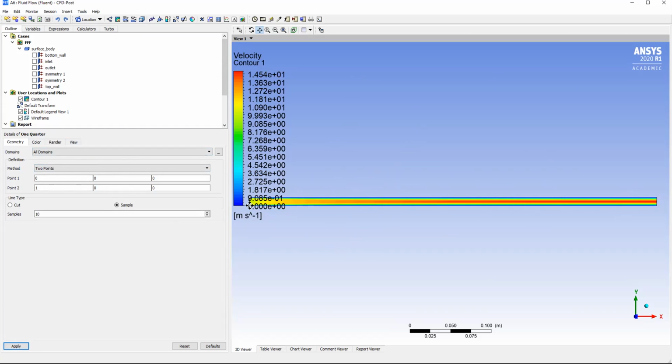So the dimensions that we have are 500 millimeters by 10 millimeters. And this part here is strictly in meters. So you have to convert all of these numbers into meters. So we have 0.5 meter for the length, and then 0.01 meters for the height. So if we look here, we have 0.1 and 0.2, and these three numbers. We have x, y, and z coordinates.